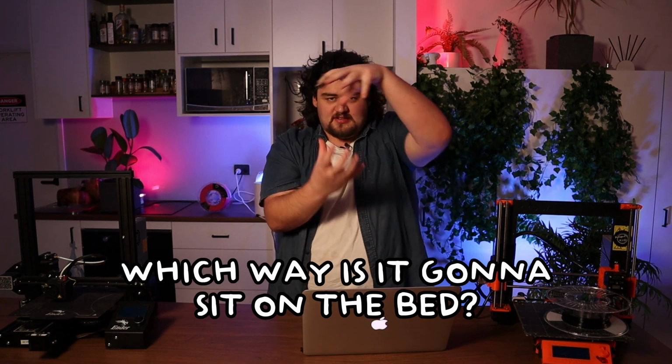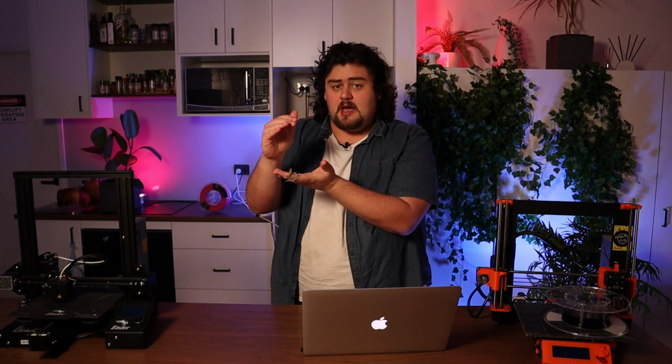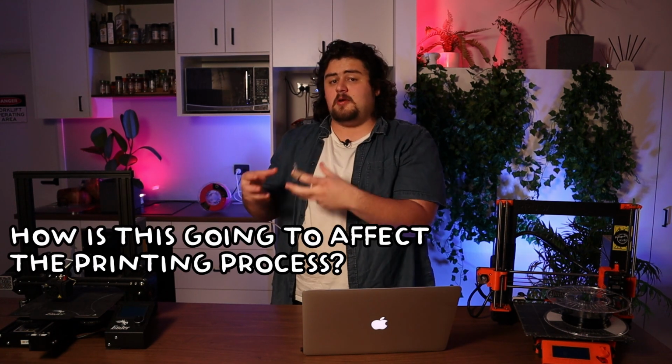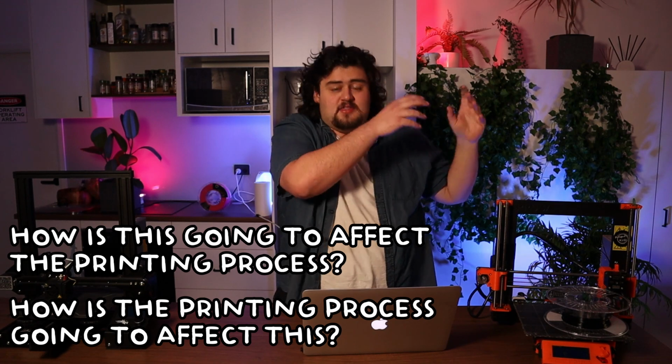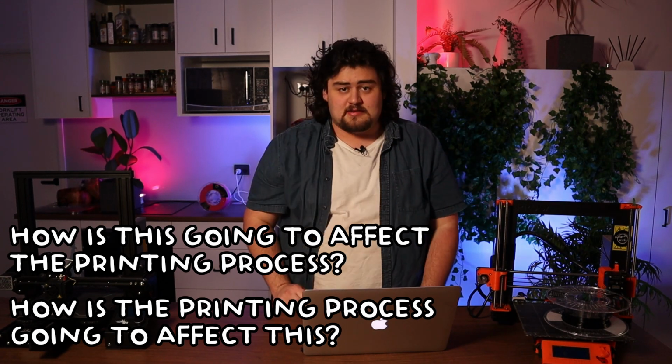So every time that you're modelling a part to be printed, you first need to figure out which way it is going to sit on the bed. And from that part, every feature that you add to build it up, you need to be thinking, how is this going to affect the printing process? And how is the printing process going to affect this feature? So let's get into some examples.